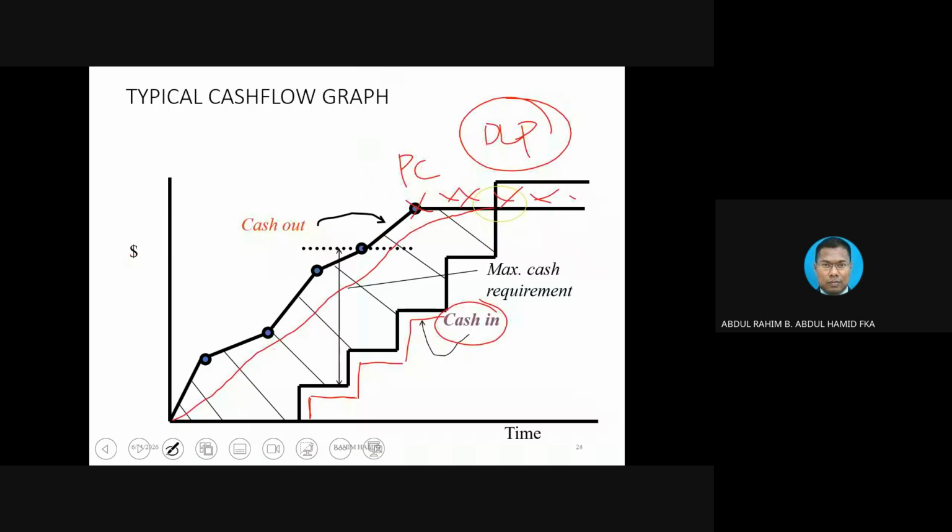Remember I mentioned to you the S curve. Basically, the way we calculate the cost is based on unit rate. The unit rate already has some kind of profit portion. The smart contractor sometimes loads profit a little bit higher at the beginning of the project activities. Why? Because if they do that, they are going to get more payment.